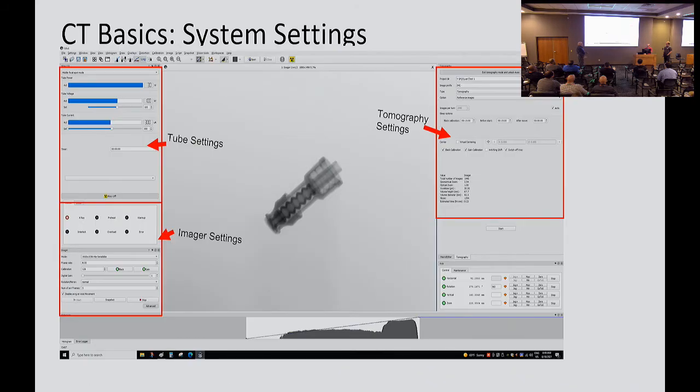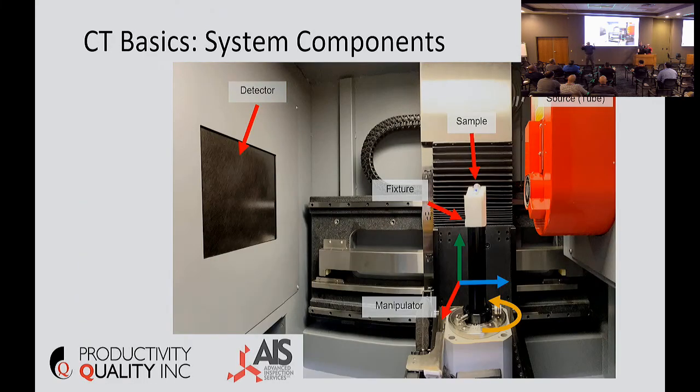And you can imagine that it is kind of like an optical comparator. You know, here's my light source, here's my part, over here's the screen. And so the closer the part gets to my light source, the more I'm blowing it up, and the better the resolution I'm going to see. Exactly. Okay.